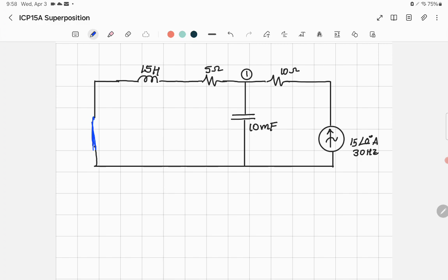Simple. There is nothing in it, but you got to be careful. You got to look at the frequency, because every time you change the frequency, you change the impedance of each element. Right. Now, what is the frequency now? 30 hertz. So you'll calculate omega 2 is equal to 2 pi f2, and f2 is equal to 30, which is equal to 60 pi.